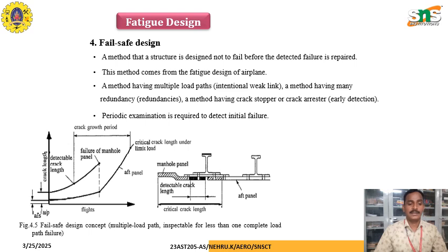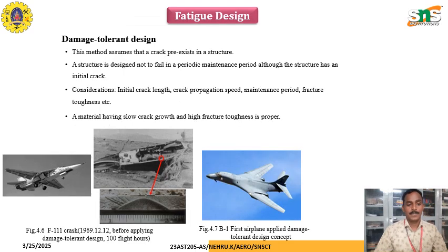Fail-safe design is another approach: a method in which a structure is designed not to fail before a detected failure is repaired. This method comes from the fatigue design of airplanes. It uses multiple load paths, intentionally weak links, and many redundancies, which are methods to make a crack stop or be arrested, and allow early detection. Periodic examination is required to detect initial fracture or fatigue failure.